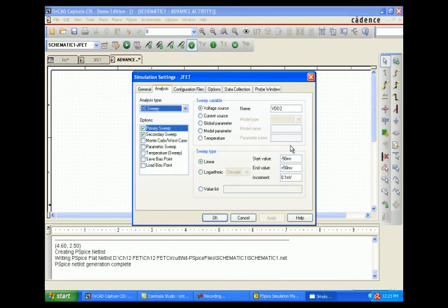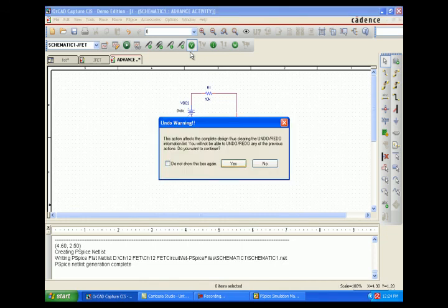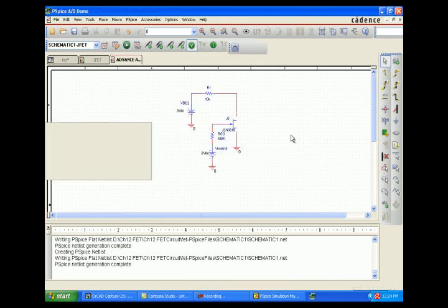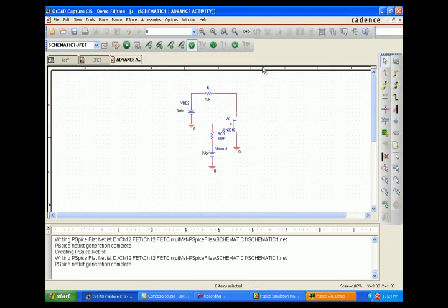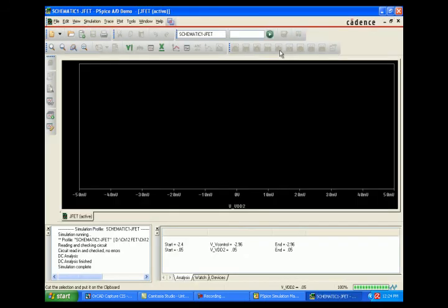Now over here VDD2, that's the starting value we're changing, and the ending values. This is the variable list we give: 2.4, 2.8, 2.9, 2.94 and 2.96. So this will be the voltage given to the gate. Run the simulation. This goes to the gate. So the VDD2 is our X parameter.